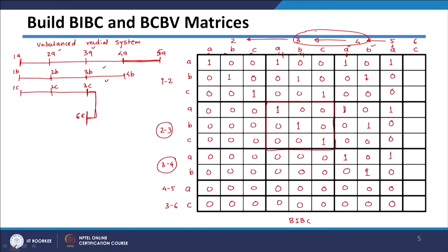And the next step, as we know, since this is branch number 4 and 5, at 4 and 5 we need to put a unity matrix. The size of this is only 1 by 1. So we need to replace this entry by 1.